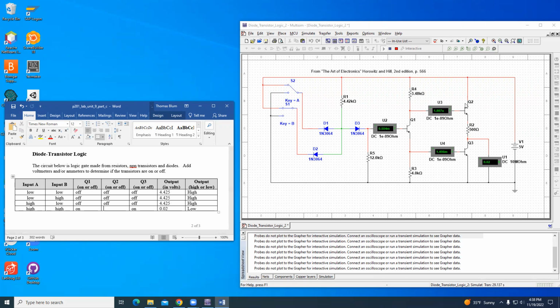The whole purpose of this arrangement here with the two transistors stacked like they are is to really firm up the state of the lower one. It doesn't matter if the higher one is perhaps not as firmly on or off as we might like. Its job is to make sure that the lower one is. I'm just going to say question mark.